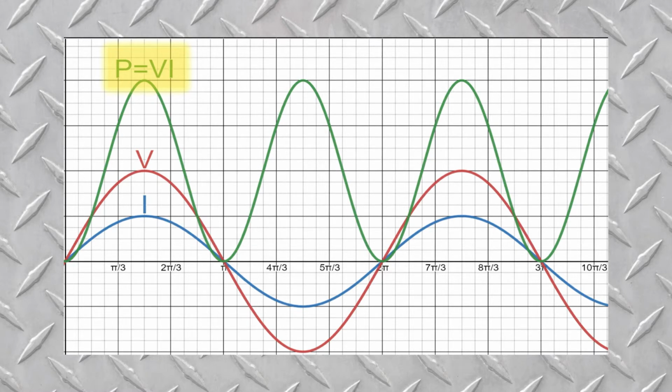But you can see that a couple times in 360 degrees, you're going to go to zero power output. So it's gone from wherever its maximum was back down to zero twice every 360 degrees, which can lead to a little bit of wobble, and if you have a lot of load on the motor, it can also lead the motor to stall. Now this brings us to the idea of three-phase power and three-phase motors.